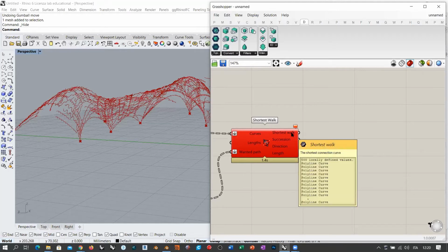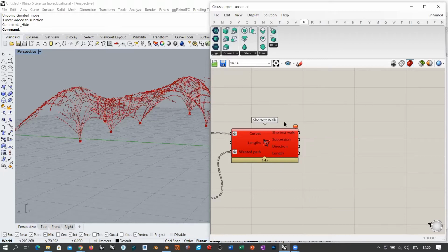So we have a bunch of shortest walks. They are 500, okay? So when I see this red thing here, it means that something went wrong. You see that it only says the start and end positions are equal. So this is something that already happened to us yesterday. Remember that when this happens, the command is probably generating a segment with 0 length.